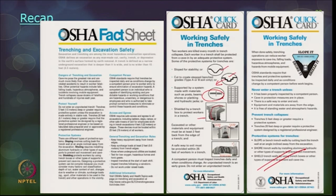Always follow a 2 feet clear distance on the edges. Clear width, and do not deposit any excavated material or equipment there; nothing should be seen there. And a safe way of exit must be provided within 25 feet of workers in a trench. So, these are all a recap of what I have covered so far.